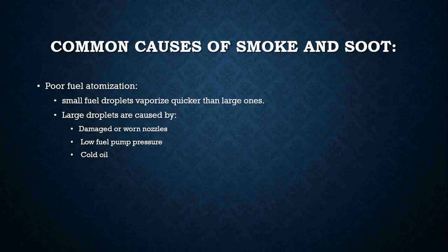Causes of smoke include poor fuel atomization. The fuel droplets are vaporized quicker than the larger ones. Larger droplets are caused by a damaged or worn nozzle, which is why anytime we're doing a service or maintenance, we are changing the nozzle no matter what.